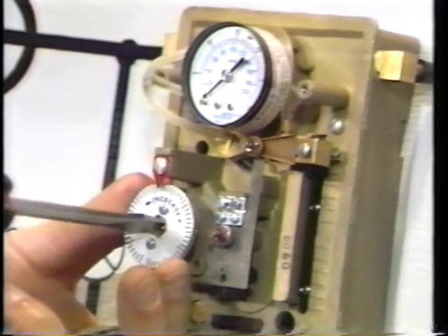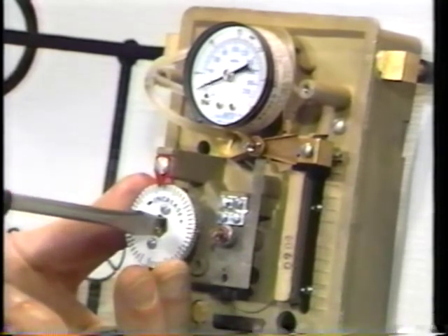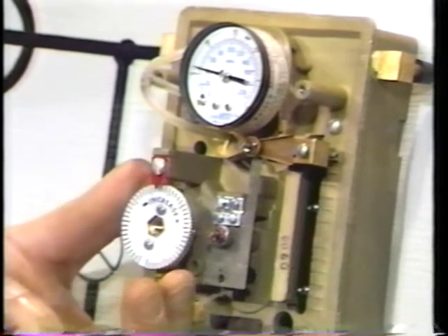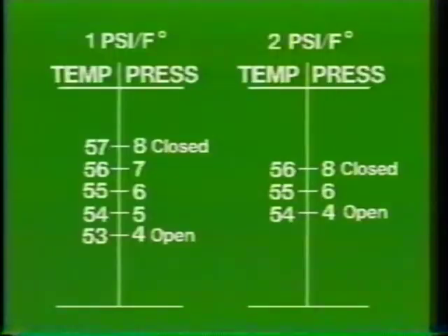Next, we set up a pneumatic transmission system and followed the 4 steps of calibration using the blank 50 graduation set point dial. And finally, we examined the relationship between the transmitter and the receiver controller. We defined gain, system sensitivity, and throttling range to help in understanding the operation of the system.